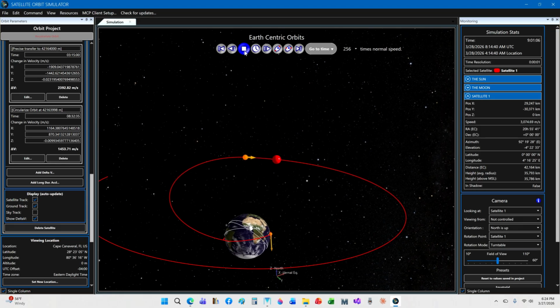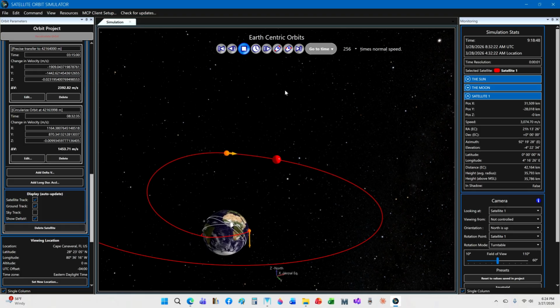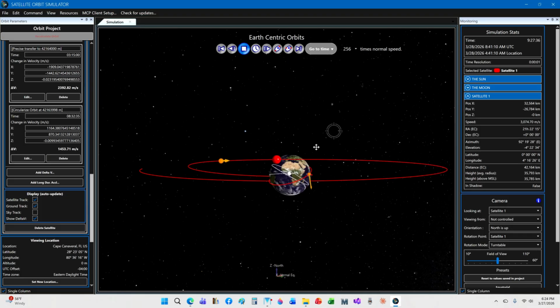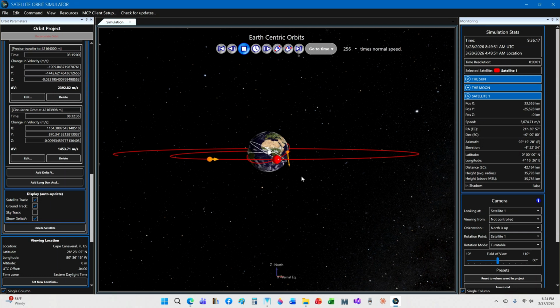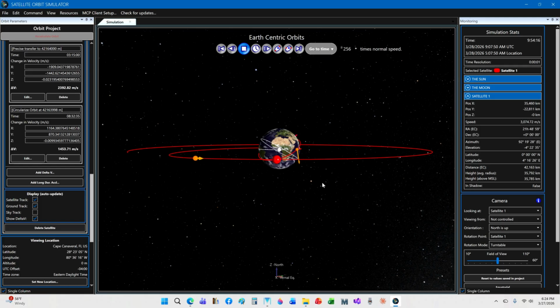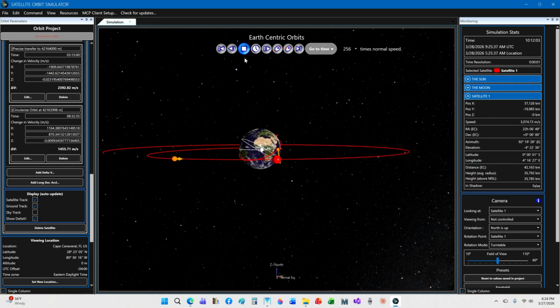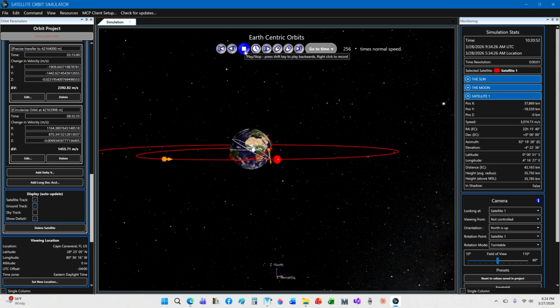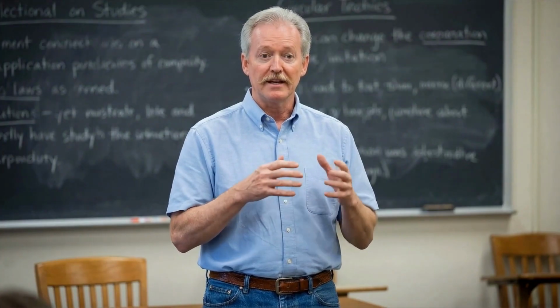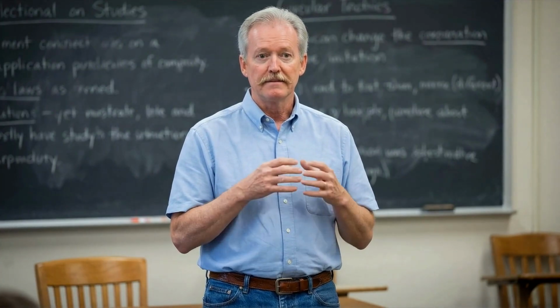Also, verify that the satellite settles over a particular longitude. To choose your own final longitude, you must change the timing for the initial Hohmann transfer burn accordingly. Note that each rocket burn, measured as a change in velocity or acceleration, is recorded for you. You can use this value in the rocket equation, along with satellite mass, to calculate the rocket fuel mass required.